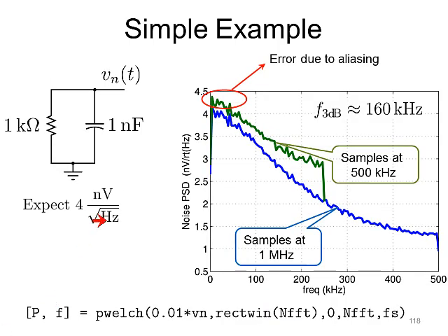And once you have the output noisy waveform, you can do periodic spectral density estimation, and this is the command you can use in MATLAB to do it.